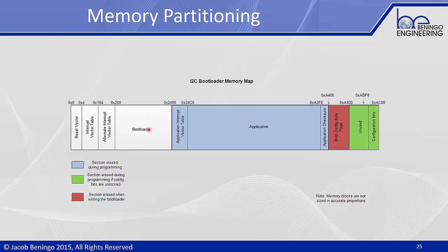If I allow the option for my bootloader to be updated, or I don't lock down this area of flash, if something goes wrong during the process, you never know. You could end up with a corrupted bootloader, in which case it could be that the system won't be recoverable, and you've essentially just bricked a perfectly working embedded system.